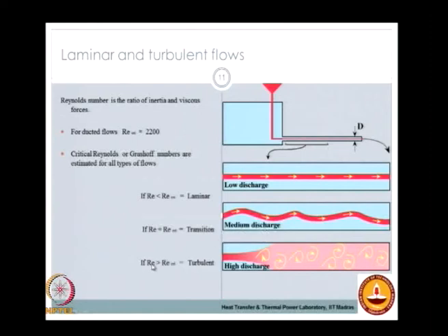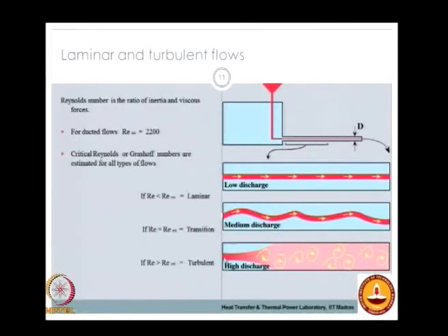At Reynolds numbers greater than the critical value, you find a lot of chaotic motion and mixing in the fluid, and therefore the dye diffuses completely into the fluid. This is the nature of turbulent flow. So when you look at heat transfer, you have to look at laminar heat transfer separately from turbulent heat transfer, because of the high diffusion happening in turbulence, which is not present in the laminar case.